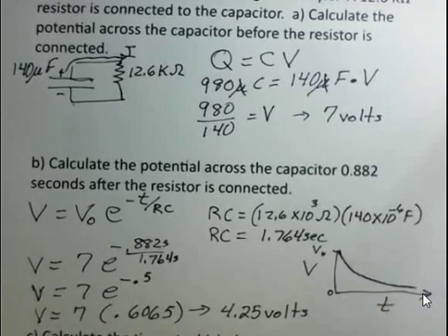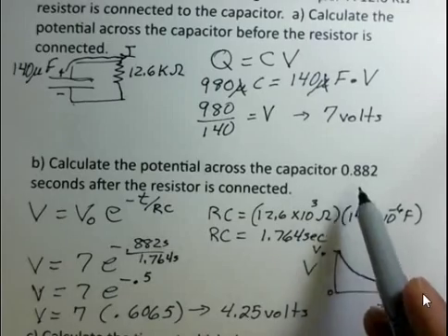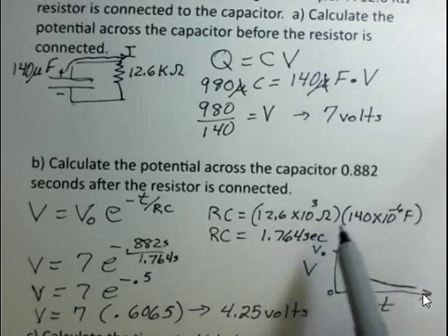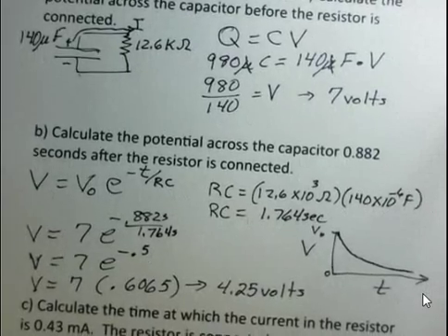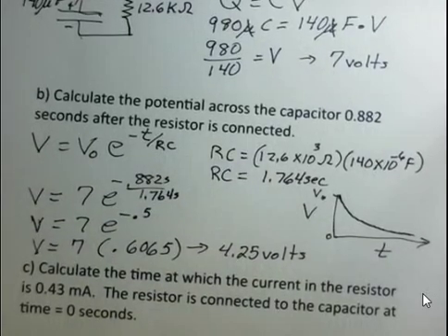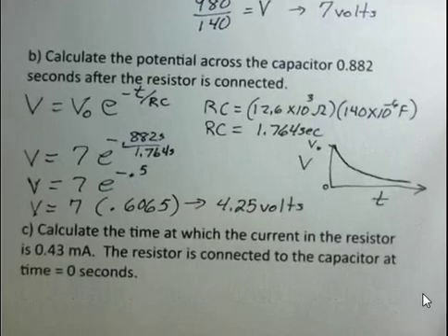So you cannot just stop by finding the RC number in seconds and deducing what fraction of the RC has been in the elapsed time. You must go through the exponential calculation.